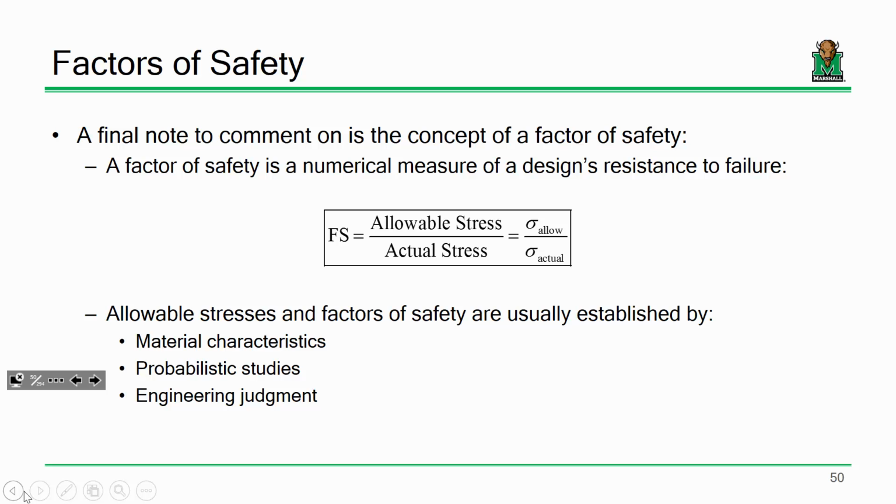When you take a course in geotechnical engineering, you'll learn very quickly that the soil properties over here can be fundamentally different than the soil properties over here. That's just the earth. I can't change that. So in order to incorporate that uncertainty, we just use a factor of safety. We just say, let's divide it by 3 and go with it. It's just something to think about. So there is a difference between what is actually the maximum available capacity in a given material and what we're allowed to use. Okay, does that make sense?